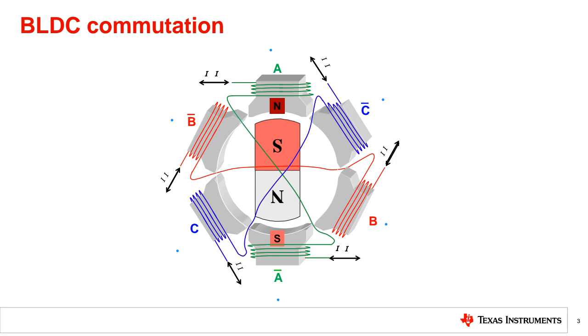The diagram on screen shows the three motor phases wound as coils on the stator to act as electromagnets when current is injected into them. Okay, for every motor coil, such as the phase A coil, there is an inverse phase A coil across from it, wound in the opposite way, which induces an opposite electromagnetic polarity.